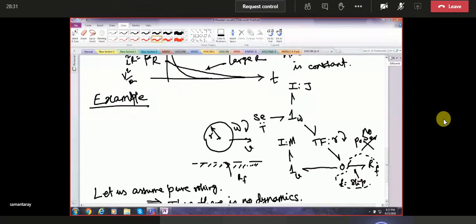Now, in that case, if we give some causality, let's say this torque anyway is 0, but it can be something. If torque is there, then for pure rolling, we must have some kind of external resistance here, air resistance or something. Once you do this, this is removed. So this is here. I will not put causality. So this comes in. This is differential causality.